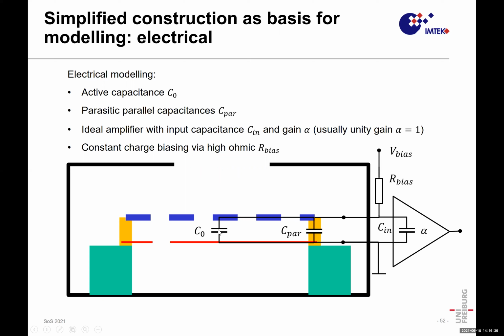I could put an arrow in between to say this is a variable capacitor. Wherever the two electrodes overlap with each other, maybe with a dielectric to support it, you will have a parasitic capacitance from that. And of course, this is not adding to the signal because it is fixed. And unfortunately, the dielectric has a higher specific dielectric constant.